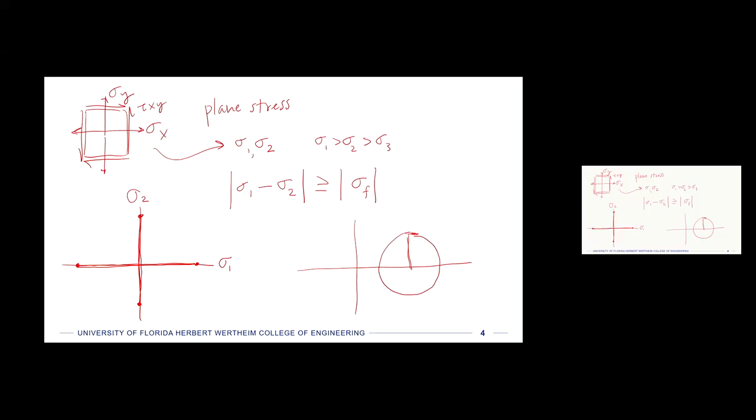Don't forget to consider 0. So we're out here. So our real Mohr's circle that has the maximum is way out here. And that's what happens if both of these are positive. So if both are positive, we can actually combine them, and they don't affect each other really when we're talking about the failure criterion. So we could draw a box like that, which is safe inside the box.